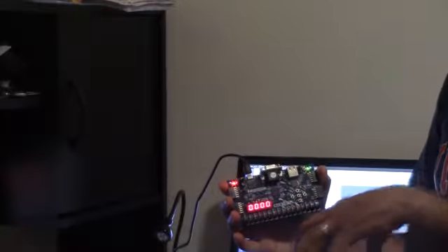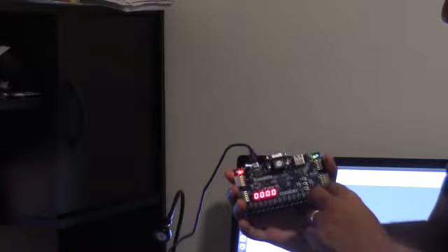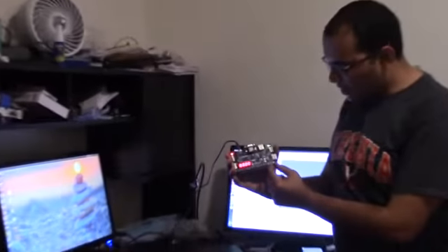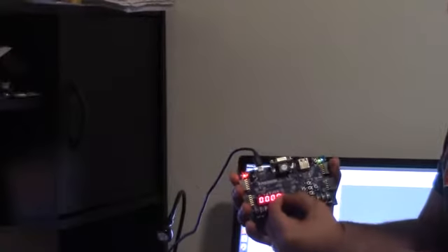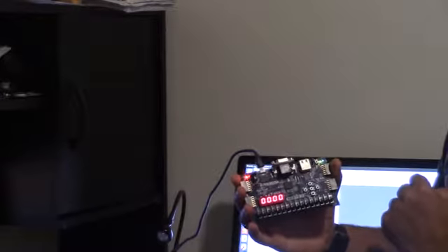Now I have uploaded the bit file, which can be mapped onto the FPGA, and based on that we will be able to see what's going on here. I would like to write on the 7-segment display, for instance, the birth year of somebody, let's say 1983. I assigned 4 switches for each digit.